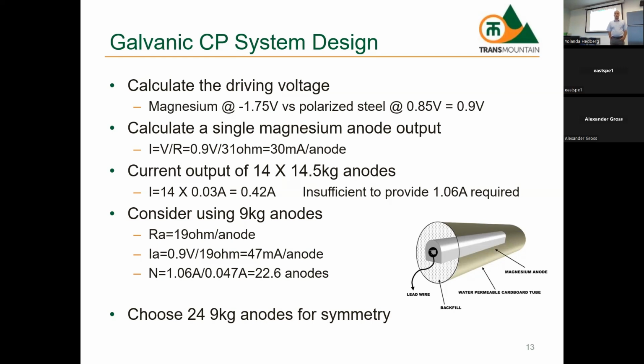Seawater, the more conductive the environment is, what you're talking about is what we call activation polarization. Activation polarization is dependent on the environment. So in seawater, what they actually do is they put anodes in place to get that activation polarization taken care of, and then after that, they don't need as many anodes.